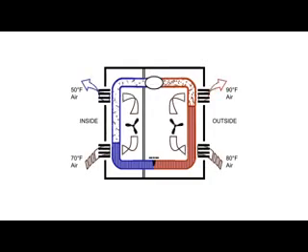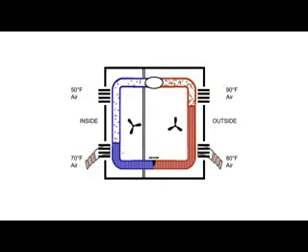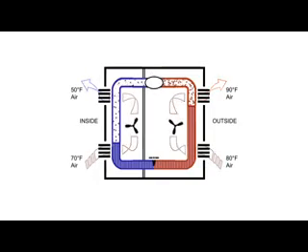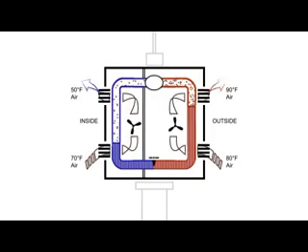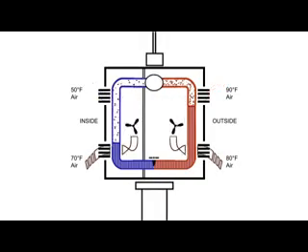In technical parlance, this type of equipment is also called a unitary system or a direct expansion system, and direct expansion is sometimes abbreviated to simply a DX system. This is a window unit, the simplest manifestation of air conditioning we see in buildings.